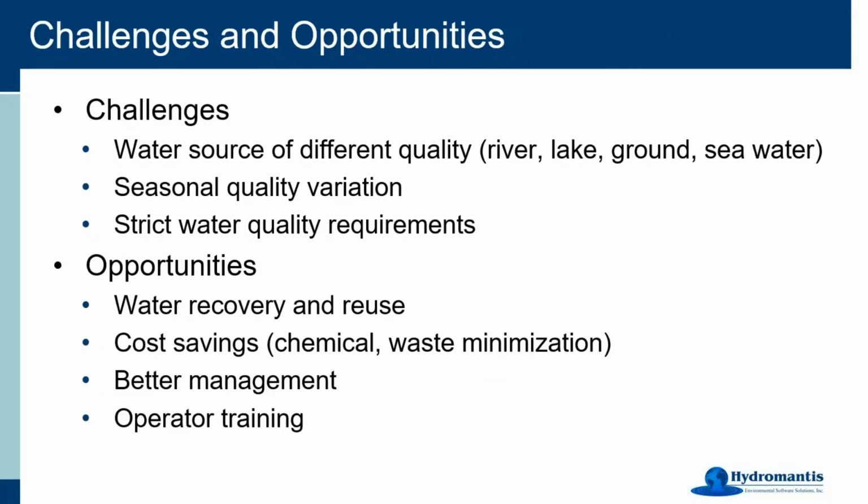If we look at the challenges and opportunities in this particular field, first and foremost, the challenges are that in working on different projects we have seen different sources of water, and the source water qualities could be very different from each other. The challenge is that you have to find the right ways to treat the water in different mixes, or when you're shifting your water sources from one source to another, you have to make the right adjustments in your water treatment plant. Also, the sources could have seasonal quality variation as well.